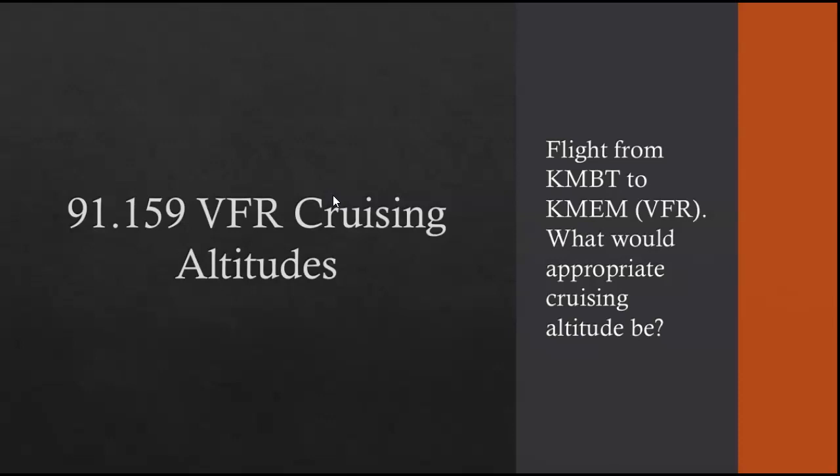So on a flight from Murfreesboro to Memphis, that would be a westerly heading. And so we should maintain an even 1,000 plus 500 on a VFR flight. So an appropriate altitude would either be 4,500 or 6,500 feet.